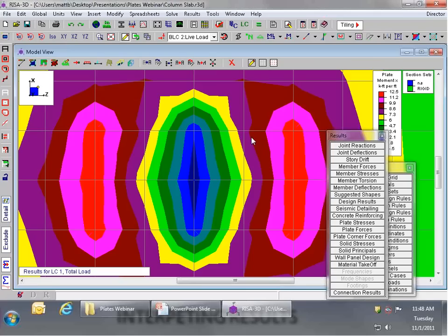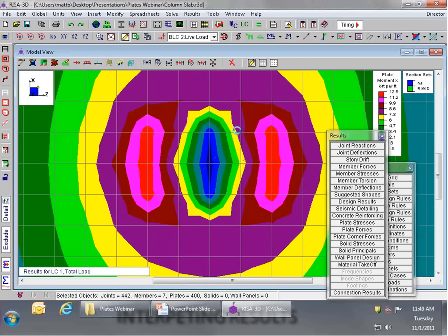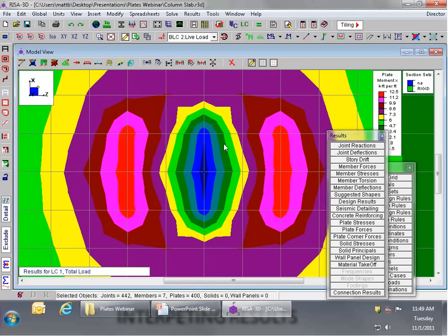Now, the issue we have is that the plate forces in this plate right here, for example, are going to have our absolute maximum moment present for the whole model. This plate, though, is actually going to have 0 plate force. It's entirely surrounded by rigid links, and so by definition it can't have any force. Now, how do you draw contours where we go from 0 at this point to the maximum value in the whole model at this point? Well, you have to cram a lot of contours in between there, and then in order to make it actually look reasonably decent, you have to smooth it out and sort of spread these contours in towards the middle. So these contours are not actually accurate values, and they shouldn't be used as such to reflect that.